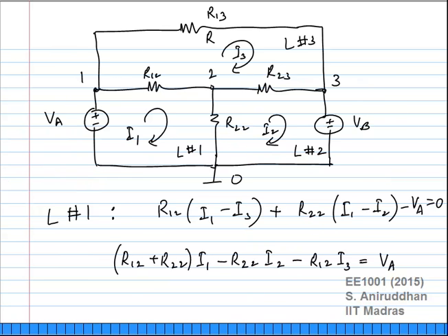Okay, let me take the original circuit. If I had actually defined this as one of my loops, what would have happened? We saw that it was still given as the same set of KVL equations because you do have independent elements in three loops. Suppose I had used loop 1 as this original loop 1, loop 2 as the one written in blue, and loop 3 as this original one in black. I would have still got the same solution. What does this correspond to? I am basically writing KVL for the overall larger loop combining loops 1 and 2. That is the super mesh we just defined, right, when you had a current source.